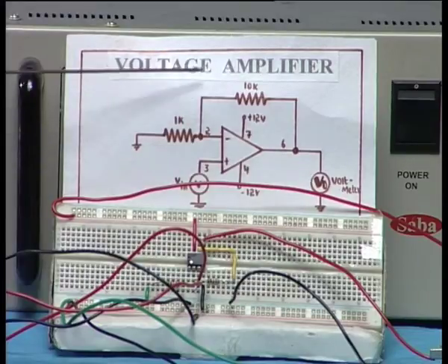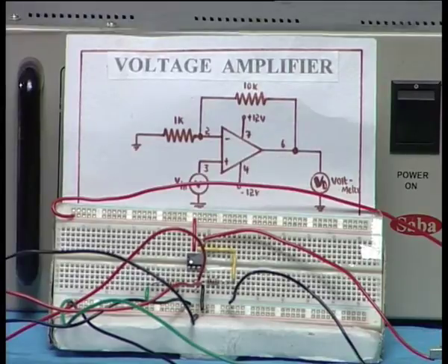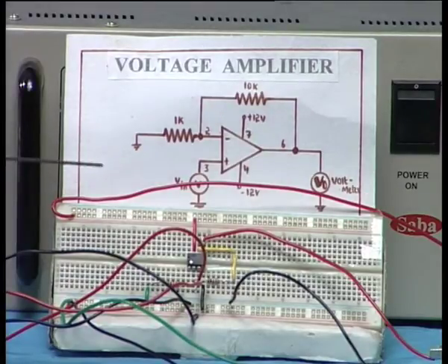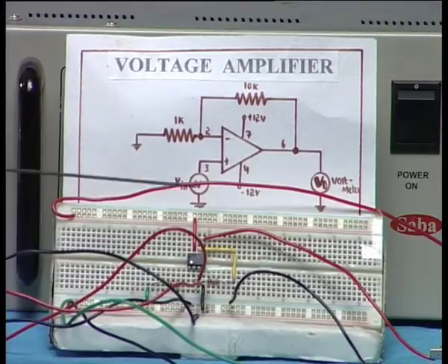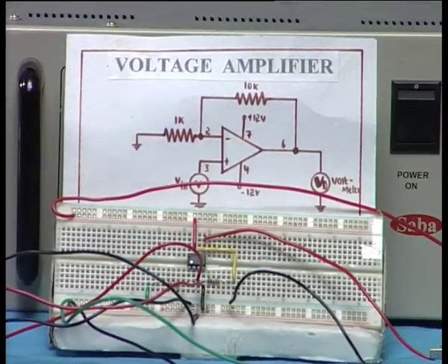So the gain of the amplifier is very easily controlled by simply two resistors, and that makes it very nice. If I have an input voltage like from a thermocouple or something, then I will be in a position to amplify that small voltage by using a very simple configuration which is not at all expensive, and with that I will be able to get amplification.